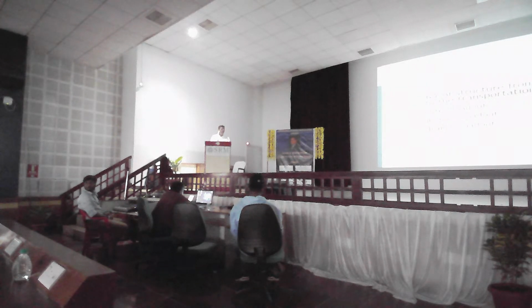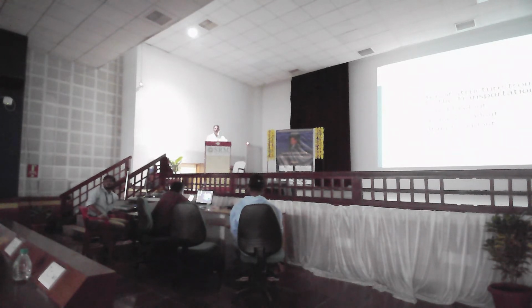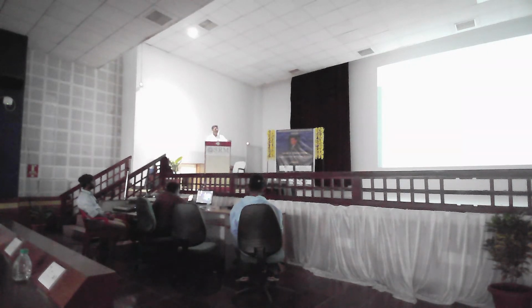As for load-out arrangements, it can be lifted and loaded out if it is lightweight, or if it is very heavy, we can skid it. We can put some rails below and pull along the rails for skidder load-out, or do a trailer load-out. You can see this image. This is the typical trailer load-out. This is the typical jacket, how we are loading out onto the barge.